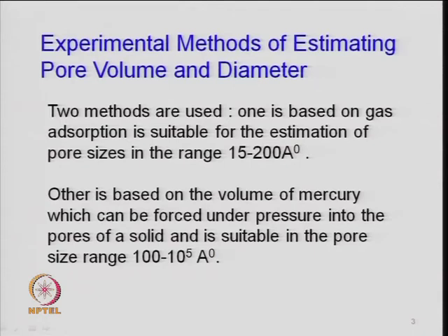When a new catalyst is prepared based on certain preparation methods, maybe co-precipitation or just the incipient wetness method, you look in terms of adsorption at the chemisorption property. You need to find out the actual pore size distribution, because the pores are selective for a given catalytic reaction. Last time we were talking about this nitrogen adsorption desorption method, which is based on the principle